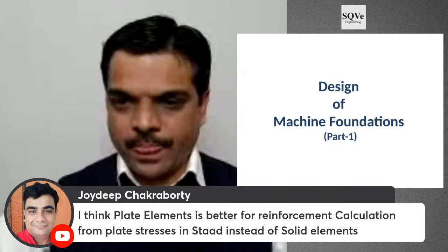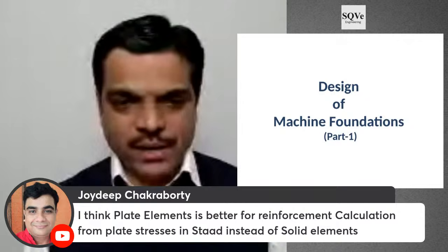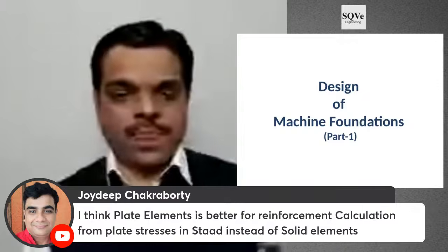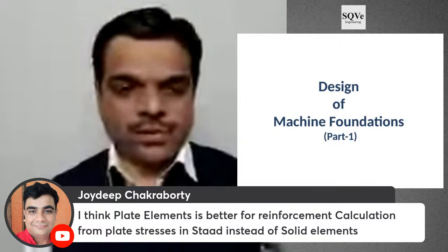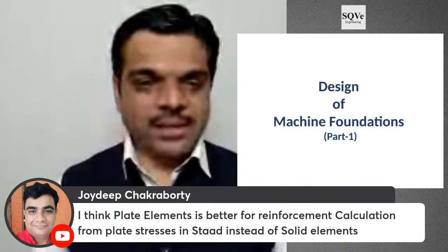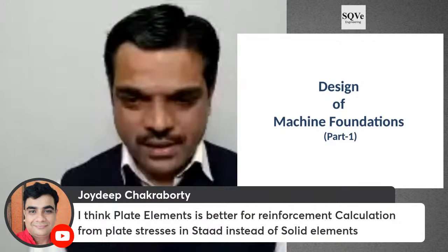Okay, Jaideep is saying, I think plate elements are better for reinforcement calculation from plate stresses instead of solid elements. Yes, absolutely right, that's a perfectly right point. Interestingly, for dynamic analysis we were creating a 3D solid element model, the one I just showed on the screen.